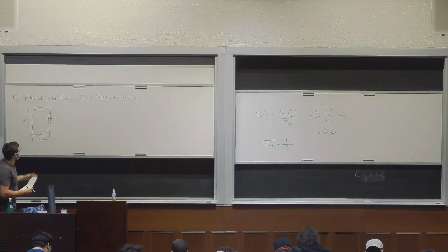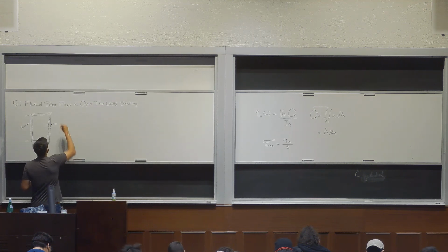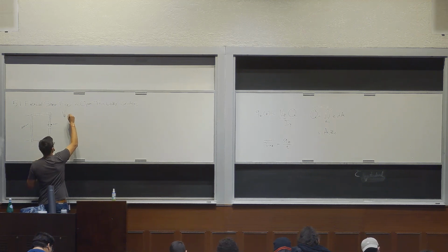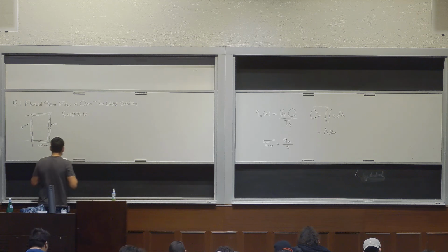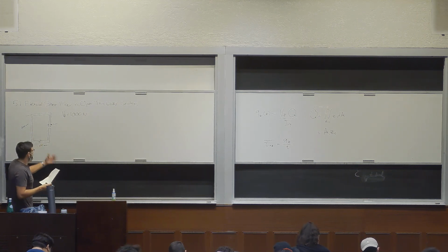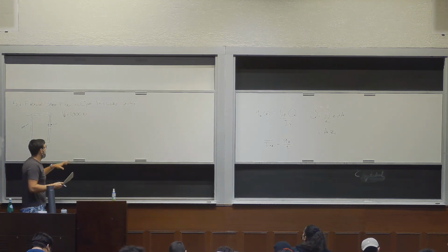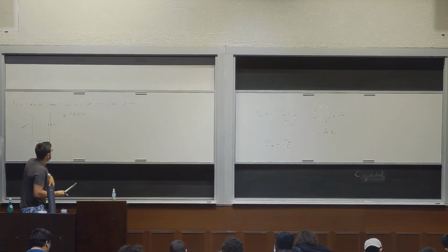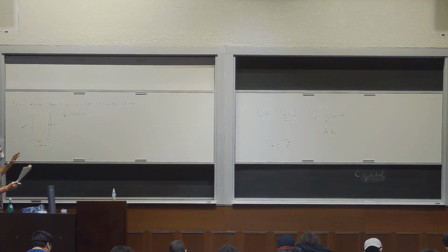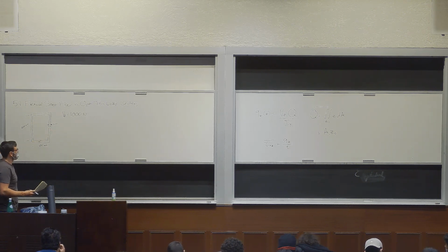And also VZ, they're giving you VZ in this case, is 1,000 newtons. And it's acting at the shear center. I'll cover what shear center is, but just keep in mind that it's a VZ that's acting on this, right? Again, just to reiterate, if you're not given VZ, but you're given a beam problem with some loading condition, you could find VZ doing the shear moment diagrams.